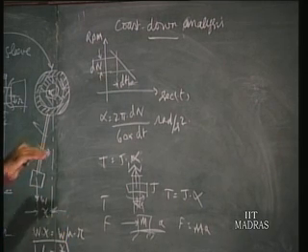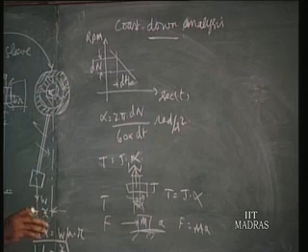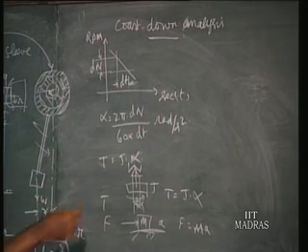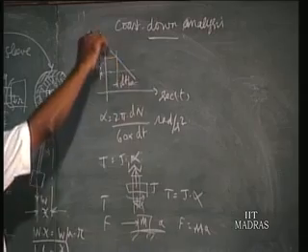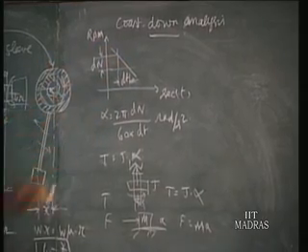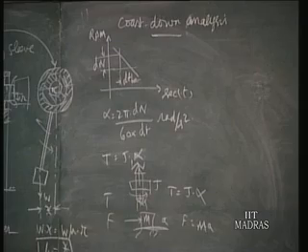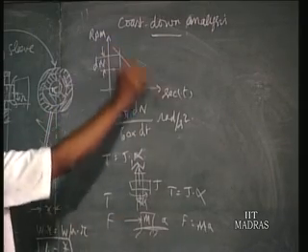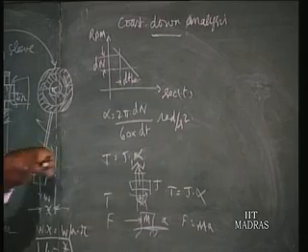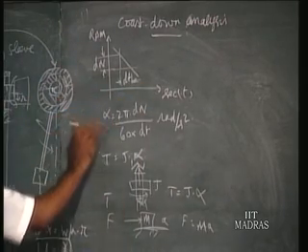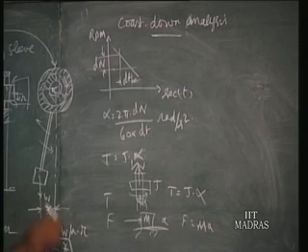Assuming that there is no windage loss in the motor, and it's only friction torque causing the deceleration, we plot the variation of the RPM of the motor with reference to time. By using a tacho generator, you can plot its voltage in a slip chart recorder. For a few seconds you let the RPM be plotted during deceleration, and from that you can find out the deceleration.